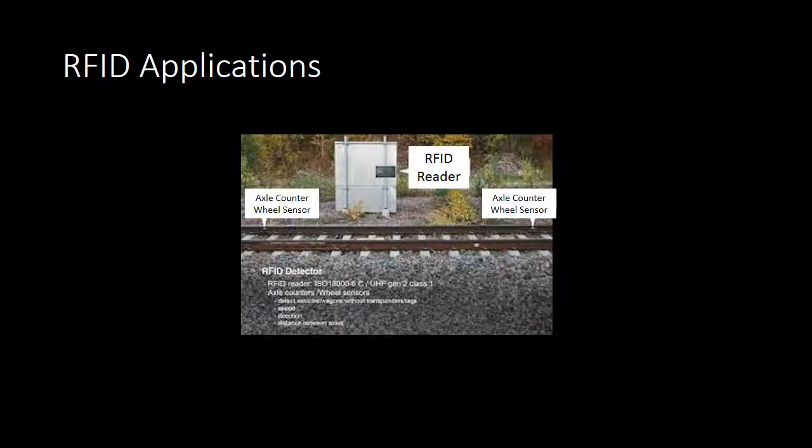Rail movements can be monitored easily by installing a single RFID reader to scan tags attached to rail wagons. These tags can contain the company information, load composition and source and destination of each wagon. When one reader is used, tags need to be attached to both sides of the wagon. Two axle counters, located 3 metres apart on the tracks, will detect wagons without tags and speed, direction and distance between the axles.